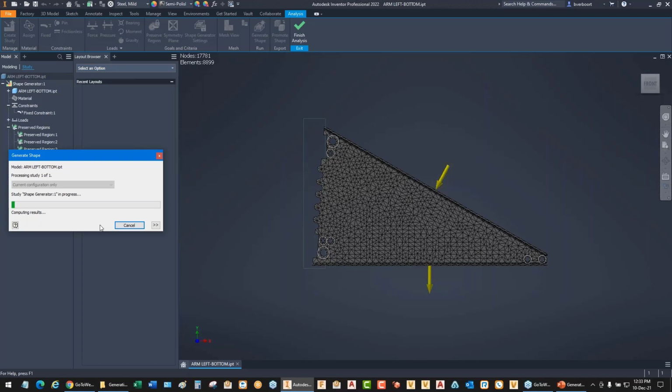For example, you set a mesh size that's so large that it wouldn't be effective. There's nothing for it to calculate against. Missing supports, missing loads, and those types of things are typically what it would find. So in finding those, you'd get the feedback in the lower portion of this dialog box, giving you some guidance as to what was wrong and a suggestion on how to improve it.